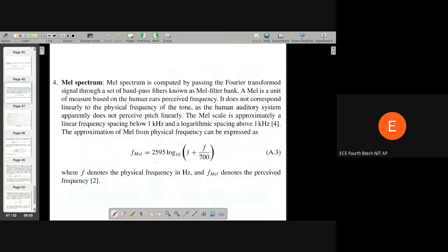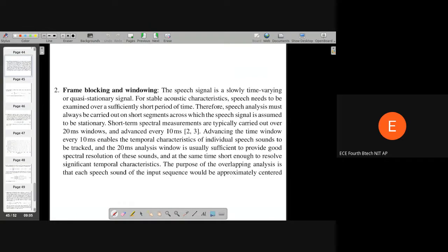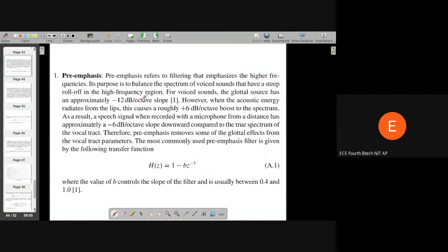So, we were discussing how to get the Mel frequency Cepstral coefficients and the step-by-step process of it. The first step we discussed is pre-emphasis. We discussed quite a lot about pre-emphasis, why it is required, and why it is beneficial, particularly from the LP analysis point of view. We also talked that speech has a spectral slope of minus 6 dB per octave.